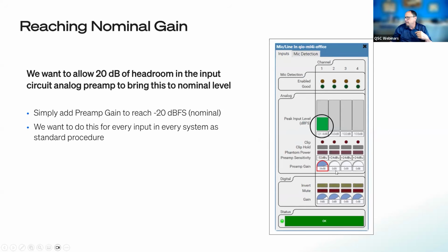And you're doing your preamp gain right here. Now, after it goes through the analog to digital converter, you do have a digital gain that you can use if you need to give something an additional bump up, but this is the key one that you want to adjust, because this is making sure the waveform is at the nominal level prior to going through the analog to digital converter. So that's important: you're manipulating preamp gain and not digital gain after the fact.